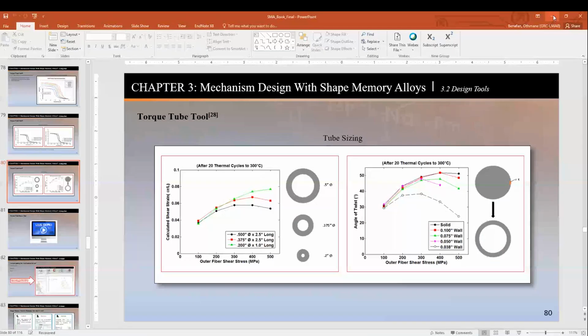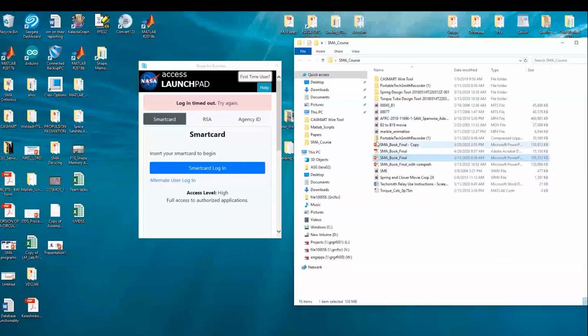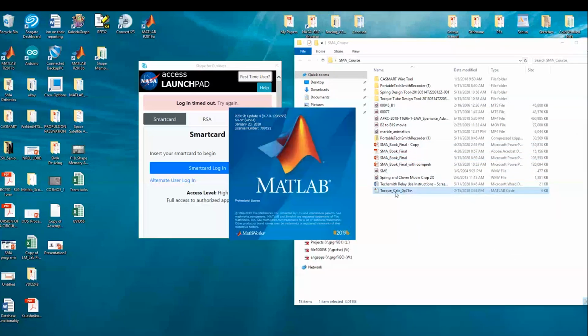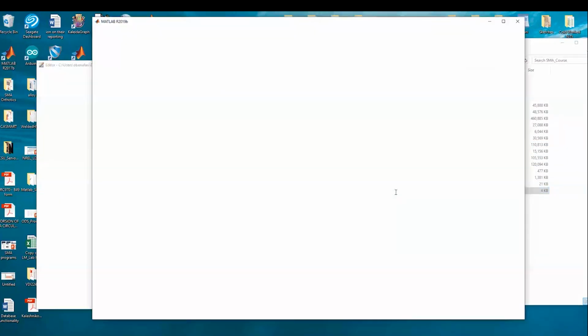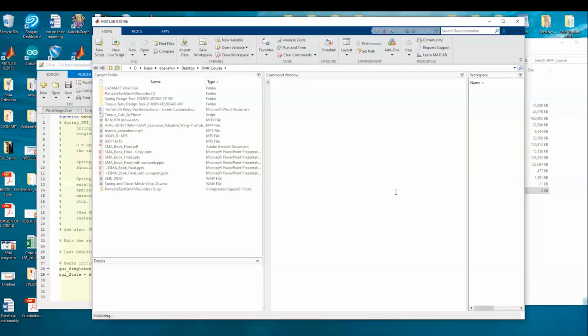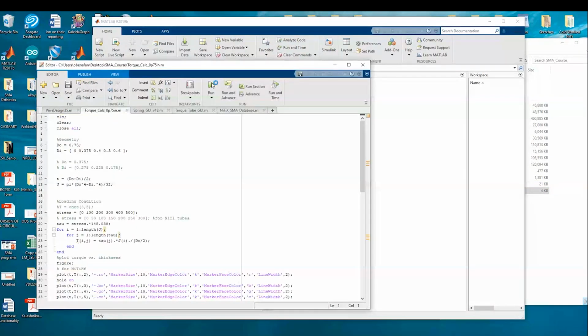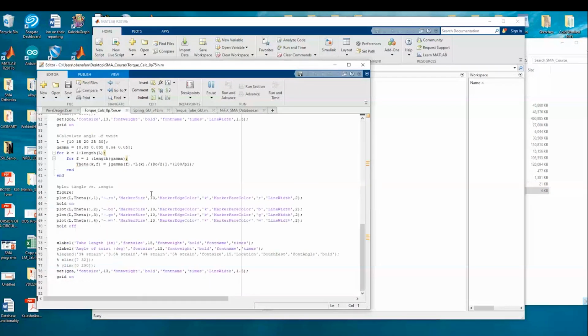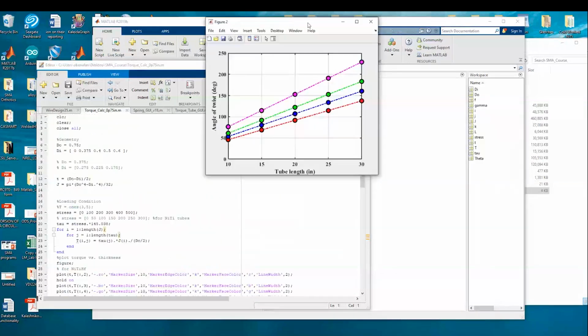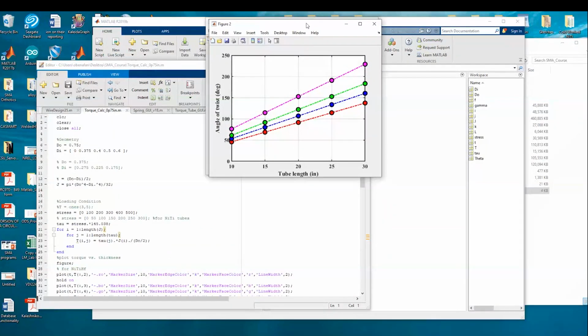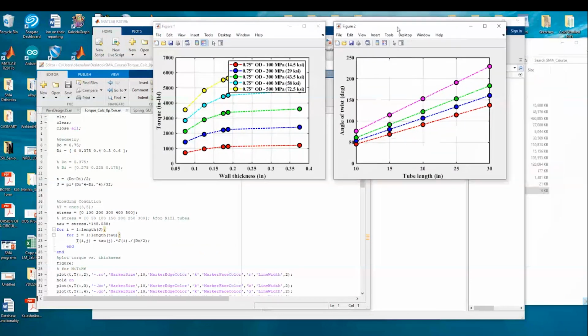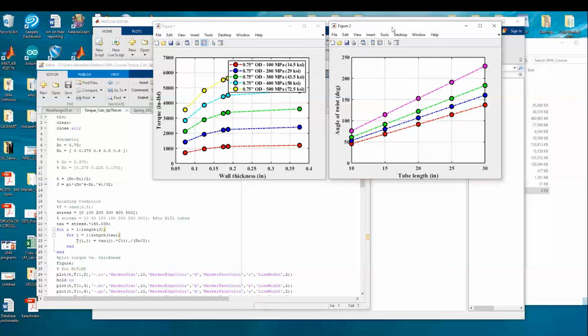So now if I go to my tube model here very quickly, I'm going to run this tube thing. So these simple calculations here, we refer to quite a bit actually. So now let's say you know nothing about tubes and you come in and you need to size a tube. You know roughly the torques you have, and you need the wall thickness and how much displacement you're going to get. So we basically boil those equations down to this.